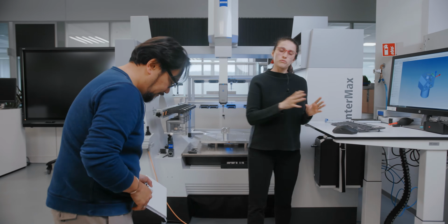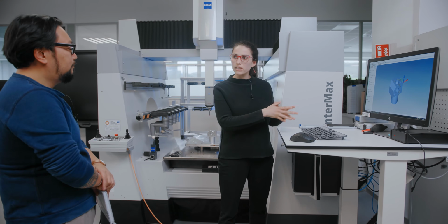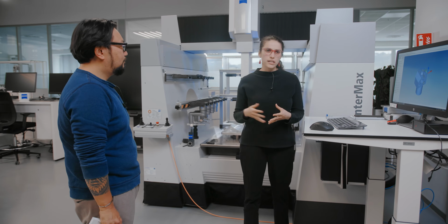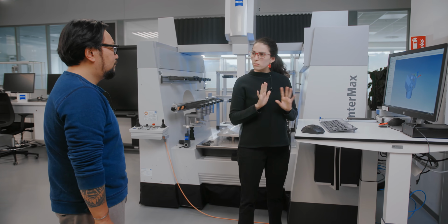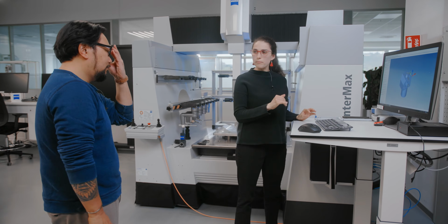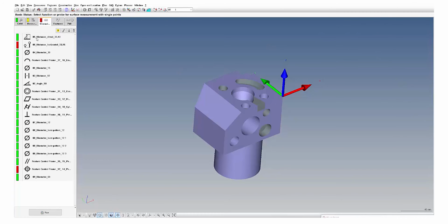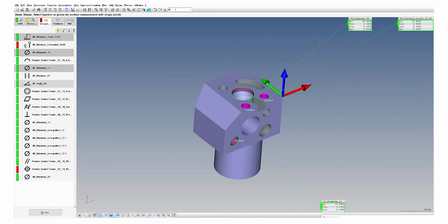So from the beginning, the CAD view will allow us to present graphically on our CAD area the measuring results, if I have features or characteristics out of tolerances or in a warning threshold. So let's go step by step how to do that. I will select some characteristics that I would like to display in a CAD view. You see I already have the banners being presented.